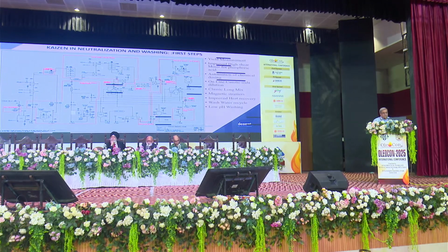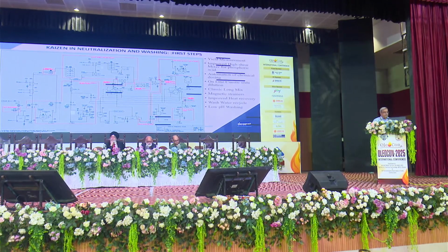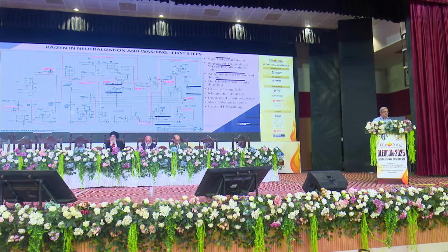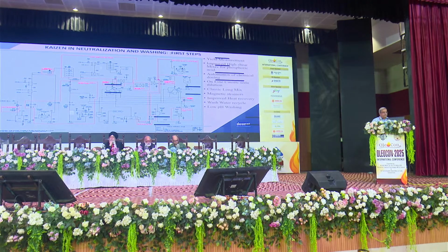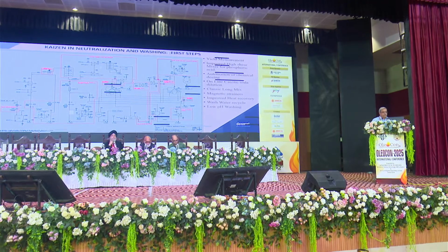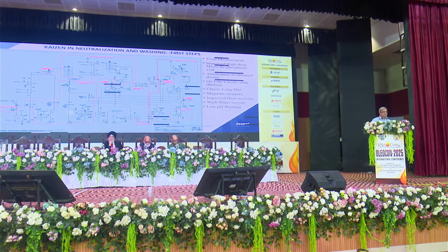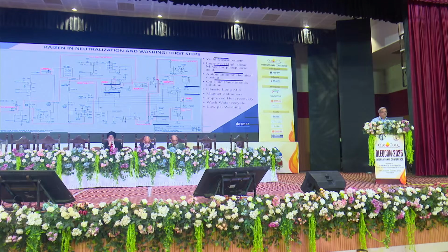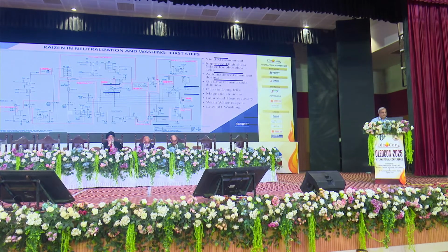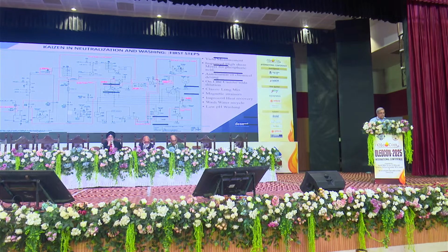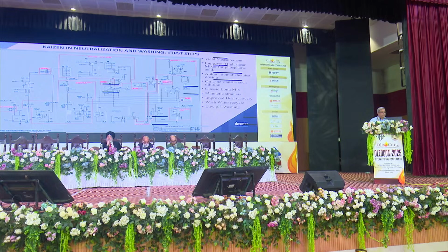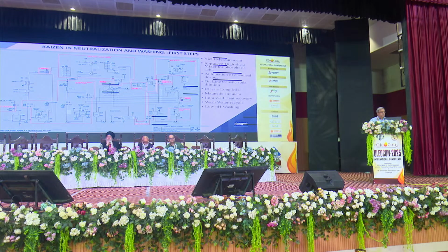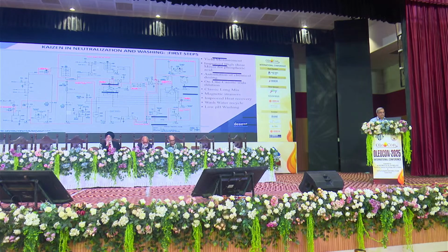It is also helpful, especially for lower quality crude oils, to cool the oil after acid reaction to around 50 degrees, have the caustic reaction at 50 degrees and reheat the oil to 85 degrees before separation, like a classic long mix. Magnetic strainers in the inlet of the separator, self-cleaning separators definitely help. We can improve the heat recovery by recovering heat from the deodorized oil before washing, because neutralization and soap separation normally happen at 80, but the washing is done at 95. This heat can come from the deodorized oil instead of consuming 15 kg per ton of steam.